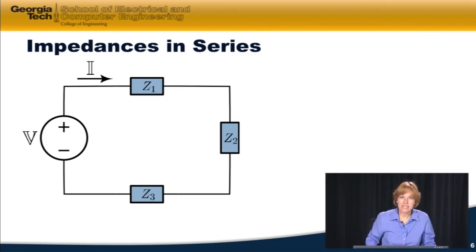Let's look at impedances in series. Here's the good thing about impedances. They're messy because they involve complex numbers, but they use all the same rules that we've already defined for resistors. So impedances in series, I treat just like they were resistors in series.